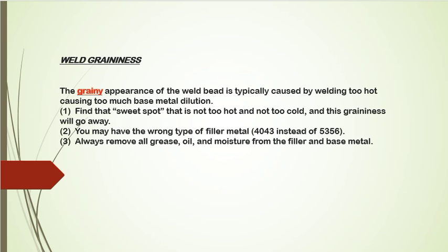You may have the wrong type of filler metal. If it is the wrong type of filler metal, you can get the grainy appearance. Always remove all grease, oil and moisture from the filler metal. So this is one of the mistakes, weld graininess.